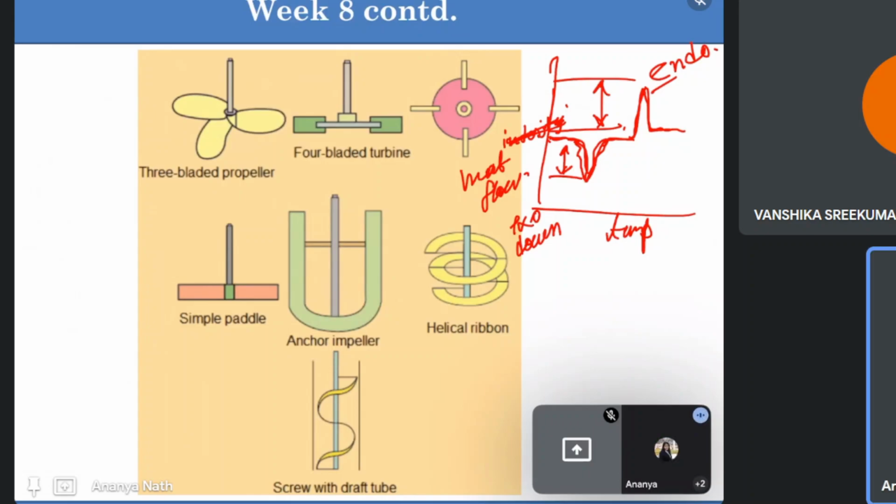Because at the time of recrystallization, we do not really need to release all the strain. You can still accommodate the strain inside the material and recrystallize, because there is the protrusion theory, where the high strain region and the low strain region will have a protrusion in between, and there the recrystallization will take place. The strain will be released in terms of heat, but it will not be that by releasing all the strain, the recrystallization will take place. As you are providing some temperature, some of the strain will be released for a certain time, and after that, as the temperature is increasing, the heat will be absorbed only, and the recrystallization will take place.